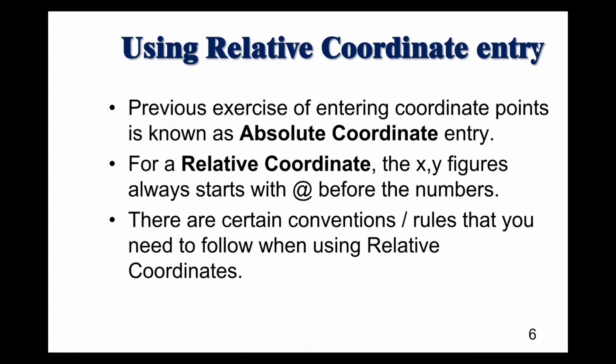Alright, the next topic is relative coordinates. In all of our previous exercises of entering coordinate points, it is known as absolute coordinate. For a relative coordinate, the x and y figures always start with the @ symbol before the numbers. But firstly, you need to understand a few rules or conventions related to relative coordinates.